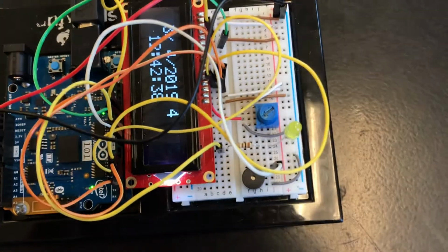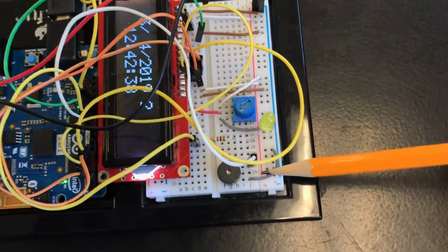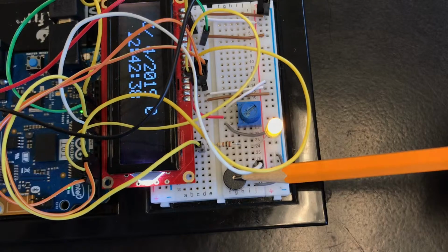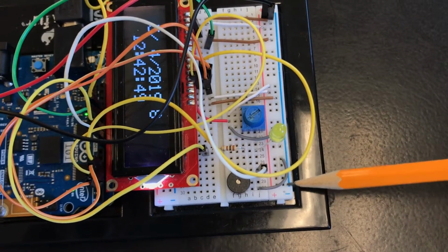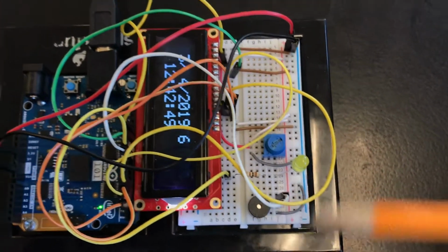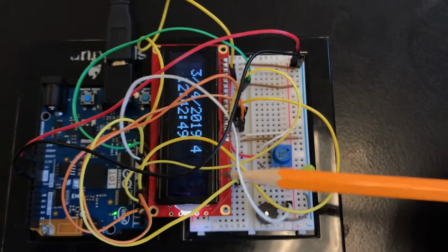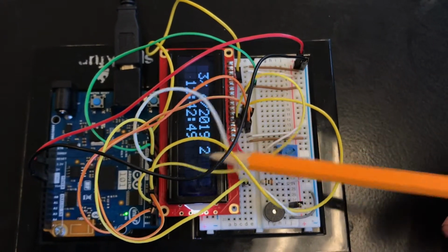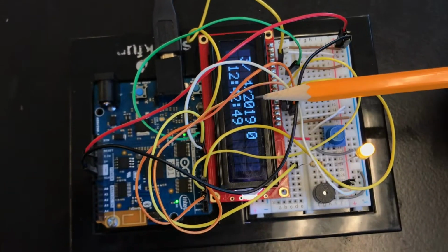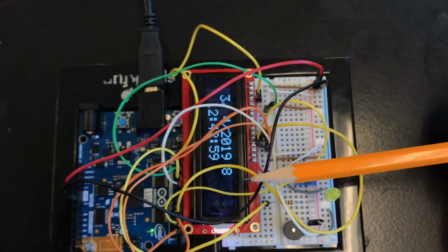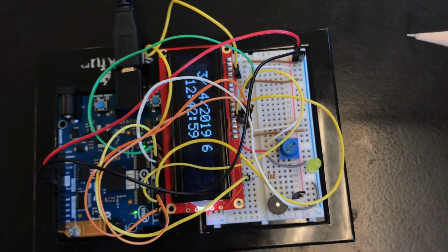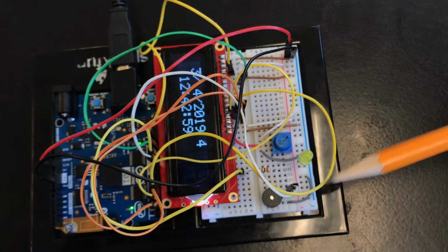And here's the piezo buzzer here. It is grounded by this gray wire here, connected to the negative side of the piezo and to the negative column here, and then it is connected to pin number 9 through this white wire here. As you can see on the board, it still displays the date and time, but now it shows a countdown for 10 seconds, and every 10 seconds the LED and the buzzer will sound.